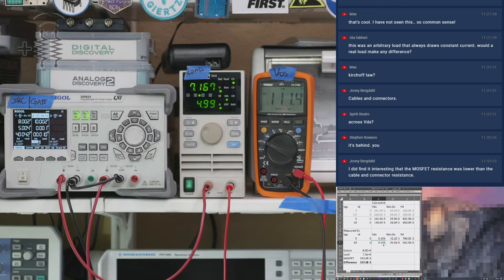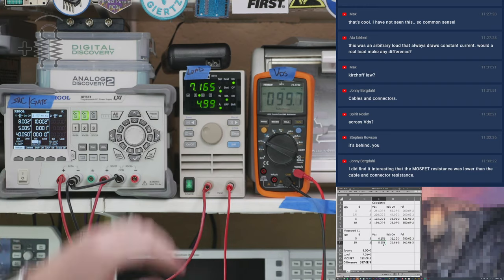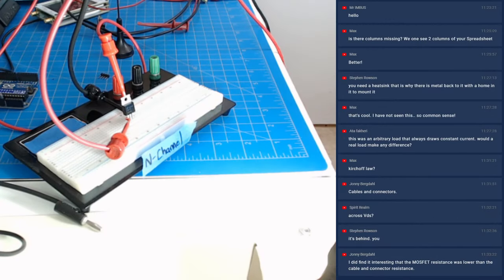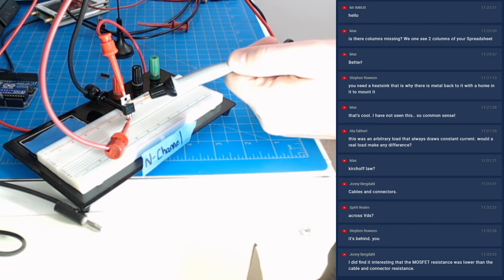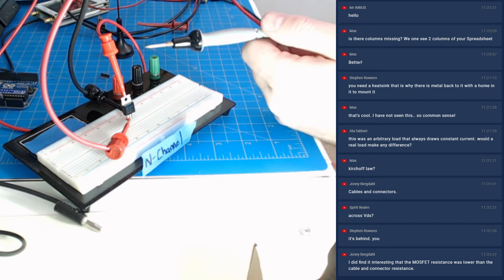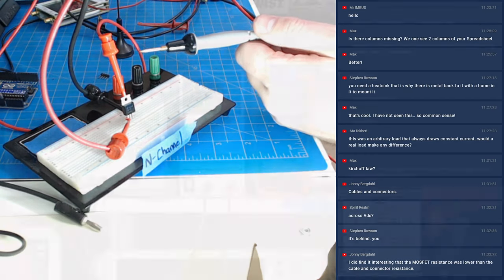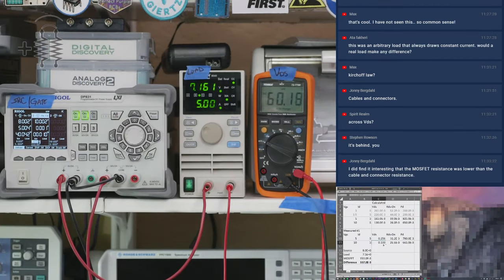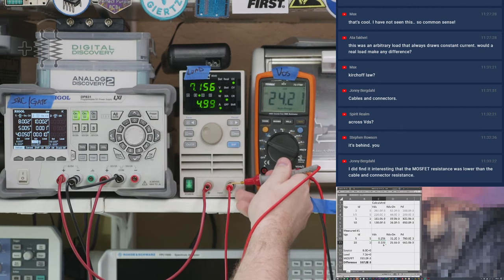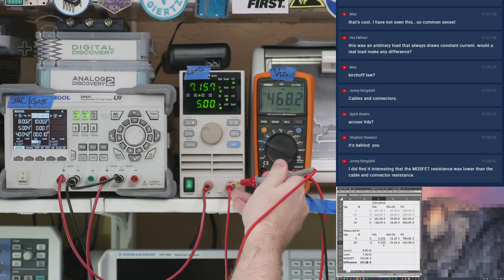Now where I'm going to measure is, let's measure the drop from the load to the transistor. So I'm going to put, so you can see what I'm doing, I'm going to take and put one of my probes here. And so this is on this wire, which is then connected to this wire up here. And so I'm going to put a probe here and a probe here.